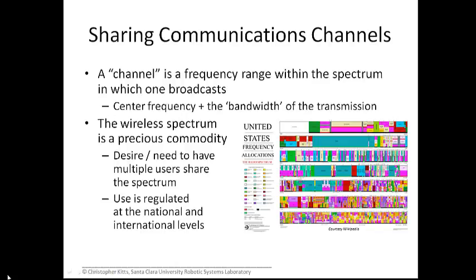And I'll point out that we are licensed operators. We're a licensed radio station in order to communicate with the spacecraft that we control. And we'll talk about that a little later, but these NASA spacecraft that we deal with typically have two radio channels. There's one at S-band, which uses really an unlicensed commercial networking sort of card, but we use it in a way that violates its license because we are magnifying it or have such an intense gain with our antenna, our directional antenna. We exceed the equivalent power level coming out of the antenna along its bore site. And for that reason, when I say we violate it, we violate the criteria that makes it an unlicensed radio.